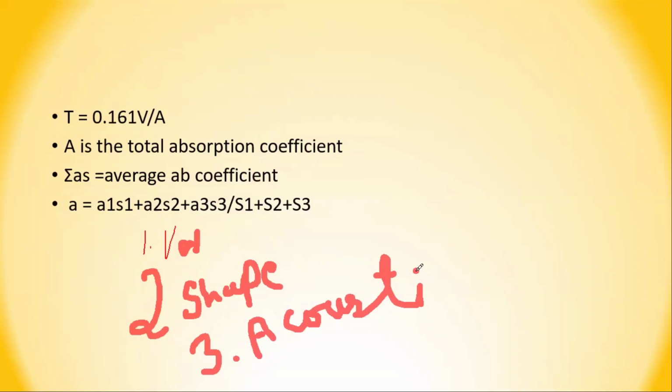So in that case, what happens? The room is empty, so there will be more reflection of sound. This we have experienced. In that case, the echoes will be produced, and the intensity of the sound will be more. So the number of audience must be as per the volume of a given room.